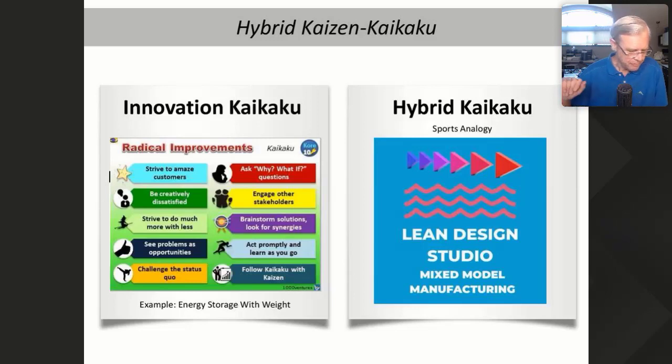Not steady. So there are a lot of ways of overcoming that. When you have excess power, one that's been in common use today in certain areas is to pump water uphill. And then when you need power and the sun is not shining, you would let it flow down and run some turbines, right, and generate power that way. So you're storing the energy in water that's at a higher level and then letting it flow down.